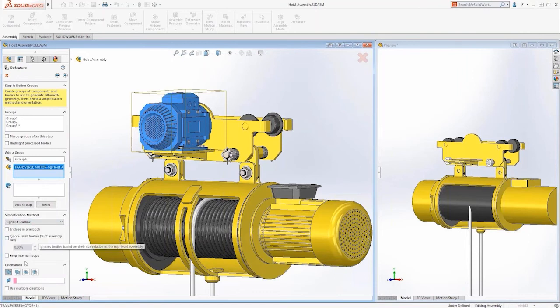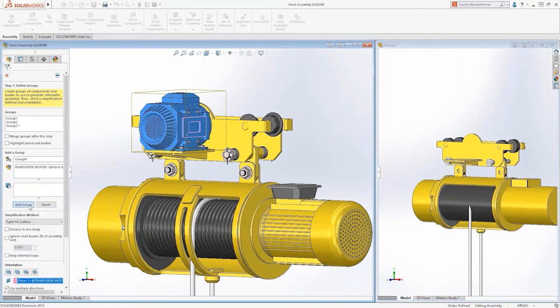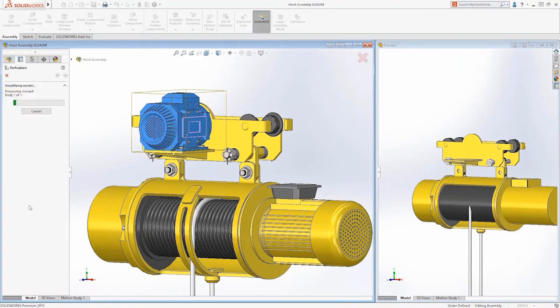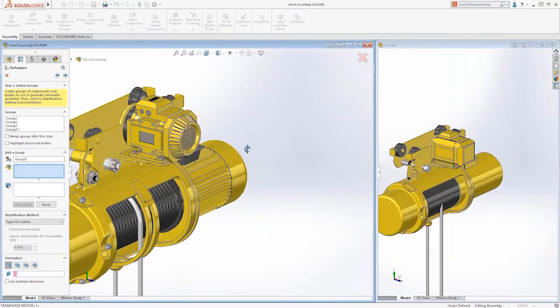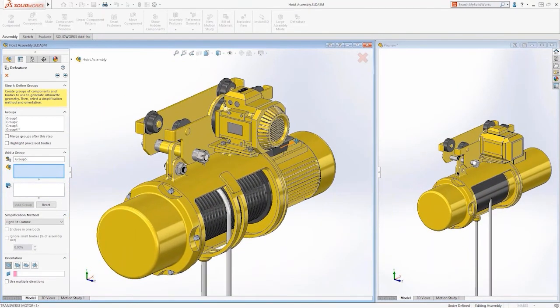This is a fairly complex looking thing here. So for this, we'll pick the tight fit, and it might take some practice to get used to selecting the correct plane, because depending on which plane you select, that's going to affect where you're going to get the performance and the detail coming in. As you can see here though, we've gone from a very complex assembly on the left-hand side to a nice low detail version on the right-hand side, but it still looks similar. You're going to know what you're looking at. You just know that you're looking at a low detail version of it.